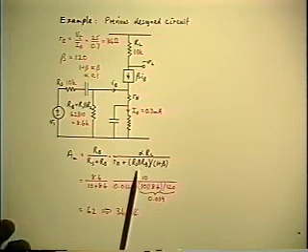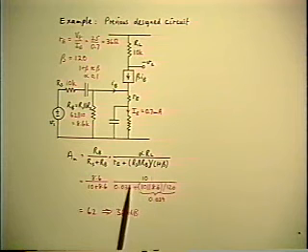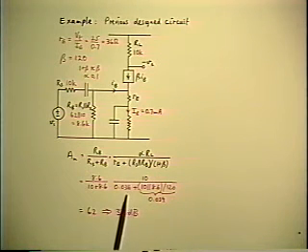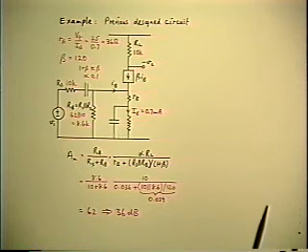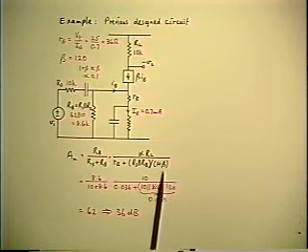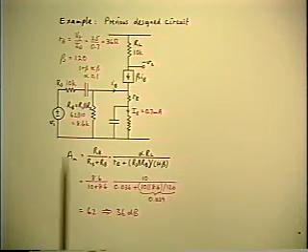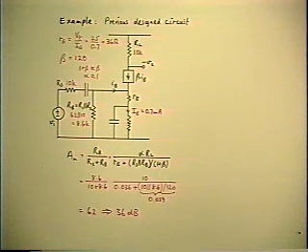So in this particular case, when you work out this denominator, the RE is 36 ohms. The other term turns out to be 39 ohms. So they are just about equal. For this example, this means that the sensitivity to variations of beta is diluted by about a factor of 2 to 1.